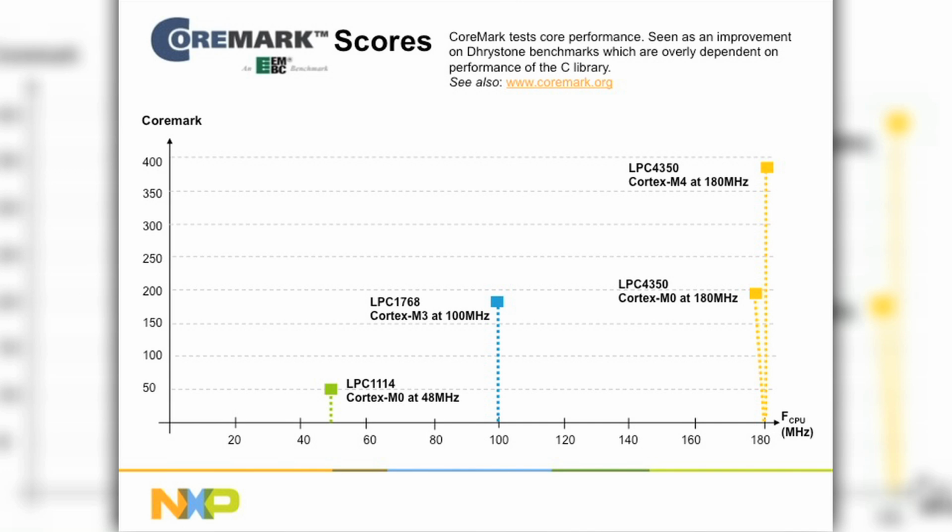And this is running out of internal SRAM. The M0 at 180 megahertz, as you see, is almost the same efficiency as the M3 running at 100 megahertz. Now, if I combine those scores, we're at a CoreMark score of almost 600, I guess, if you're looking at the two.